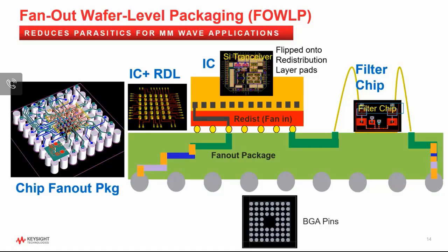Thanks, Jack. Now let's see what impact the industry trend towards millimeter wave frequency applications such as 5G, automotive radar, and WiGig has on packaging. At millimeter wave frequencies, losses and parasitics of bond wires become excessive, and wafer-level packaging is required to integrate multi-technology RF modules. In the next demo, Jack will show how to assemble and route interconnects with interactive design rule check through a wafer-level package, and then EM simulate selected nets without modifying the layout.